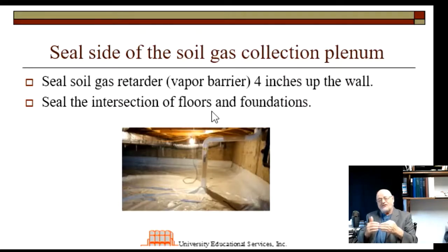And then there's a diffusion coefficient for radon through concrete. That is, while the concrete looks really solid, there's a lot of space in there for the radon to actually percolate right through the concrete, through the empty spaces in the concrete. Now, it's much more difficult for it to percolate through concrete than it is obviously through air. So the concrete does produce a pretty good barrier.